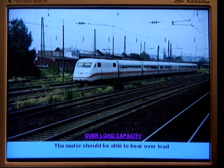For example, the train is moving on a path. At any one station there is a possibility of heavy passengers. Even then the motor can bear it easily, such that we have to design our traction motor. The motor should be able to bear the overload conditions. It is a required characteristic.